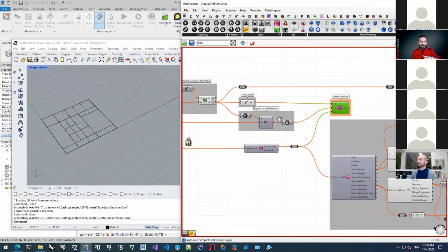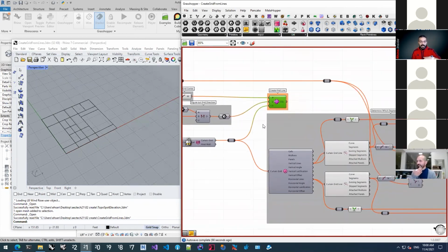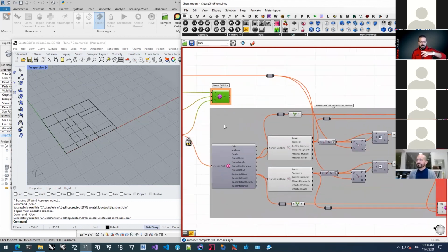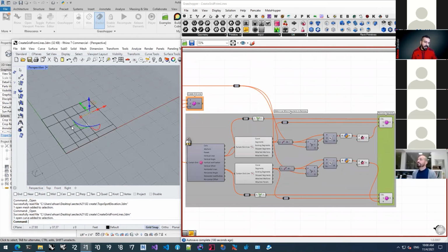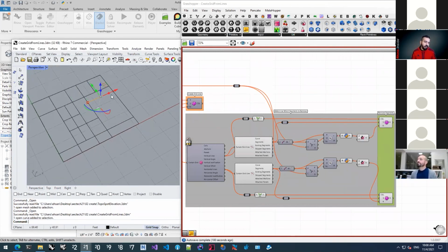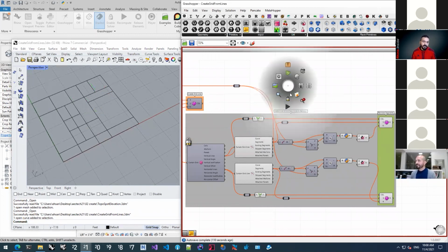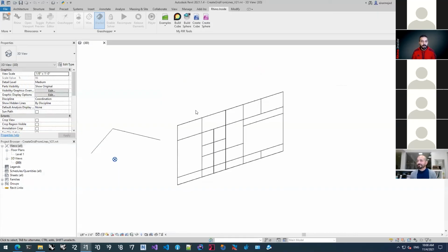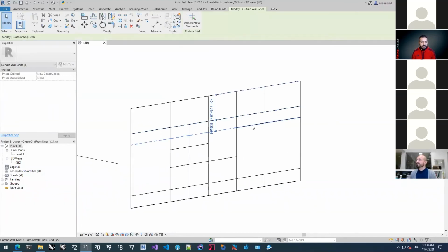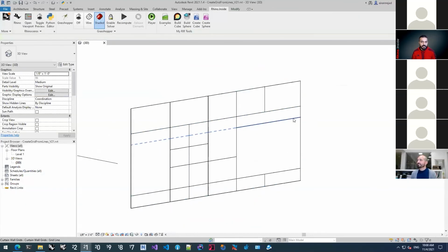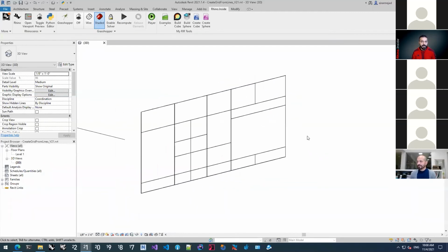So most of the time you're actually calculating this. And then once you've created the grid lines, you can place the mullions and, at the end, remove the segments that you don't want. When you create a grid line along this line, Revit creates a full line, so you have to go about hiding the rest of them. And if I run this, I get that pattern shown on the wall with grid lines and all that. So it splits those panels properly.